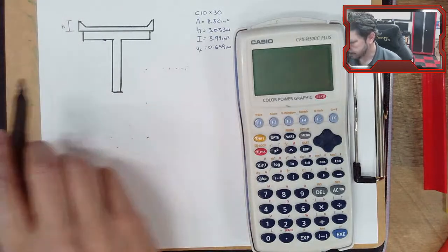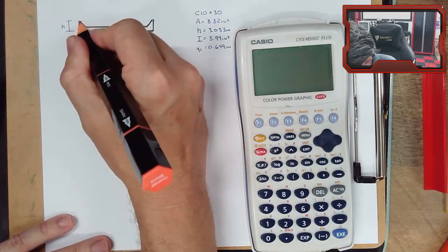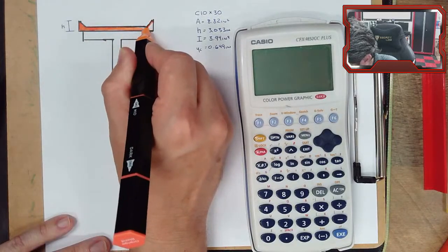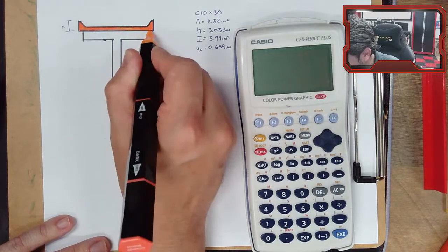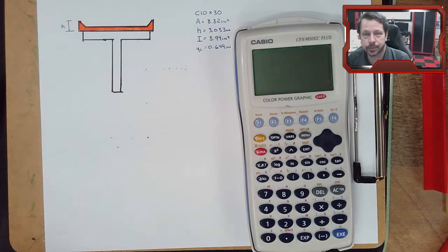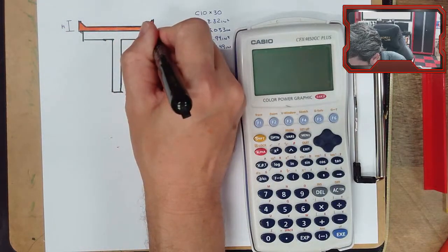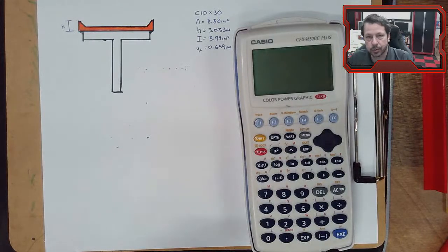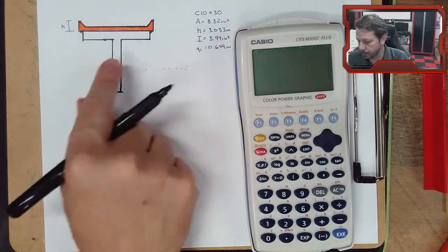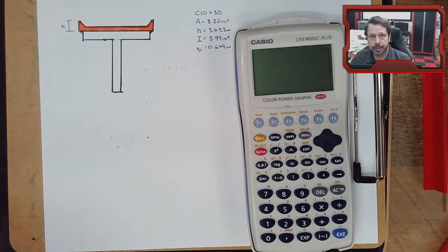All right, so here is our channel up here, just to separate them a little bit, welded or glued, or somehow fastened, and it's pretty solidly fastened. They're going to operate as one composite beam. So there's some kind of little welds in here or whatever. We're not analyzing what's going on at the actual weld. That would be this interface between the channel beam and our homemade T-beam, which would be a good place to analyze that shear stress between the layers.